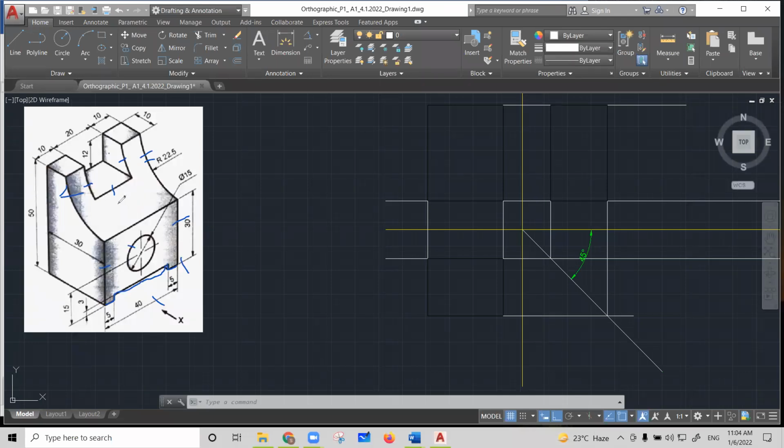Okay, suppose we name the surfaces 1, 2, and suppose in addition you mark this circle as 3. So this is one complete surface. If I mark the lines here, you can easily understand that this is the surface visible to you. I'm highlighting it with the sectional line here, just an inclined line. All right, so this surface is visible to you, as well as this one. Your circle is visible but it's a hollow one, so I'm not going to take those lines here. I hope you understood what exactly is visible from the front view side, right?